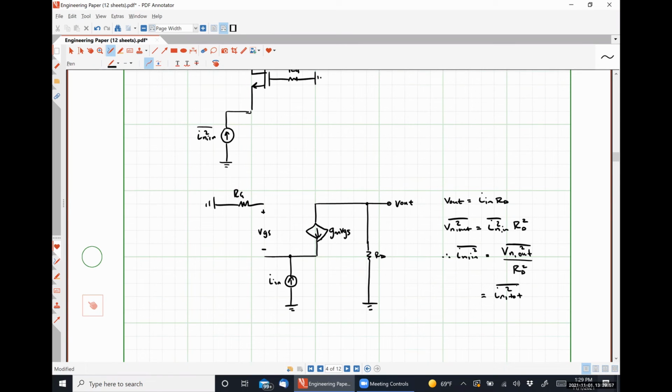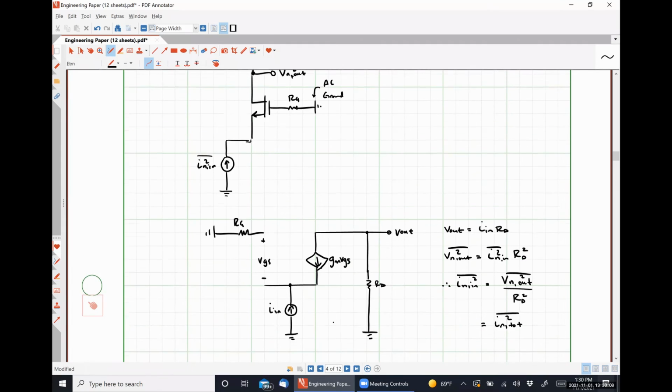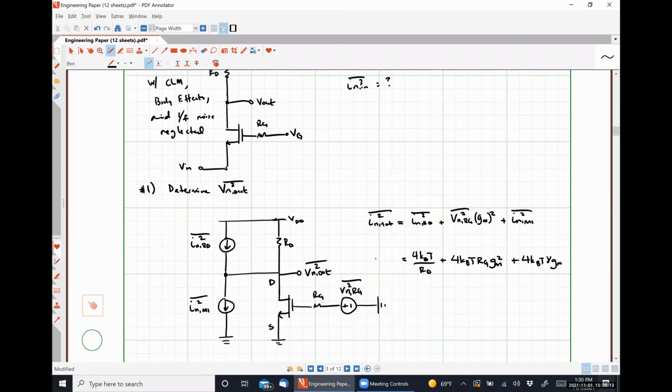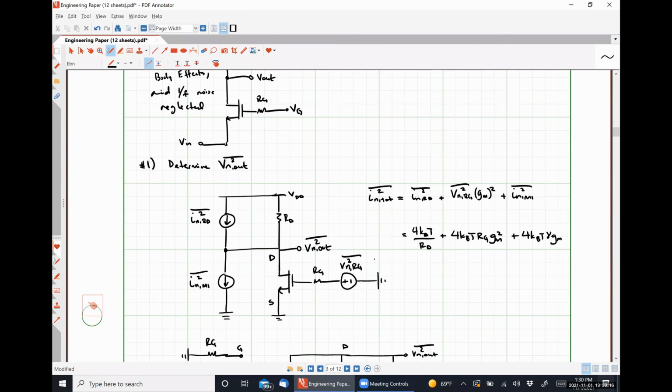Where did you say that IN total was from? Back, like a step one? Between the source and the drain. Right? So all of that, so let's go back to that, right? Okay. Well, so between the source and the drain isn't really a good way to put it. Between the drain and ground. Right? Because a portion of it, literally the transistor current itself, IN-M1 is legitimately flowing from the drain to the source.